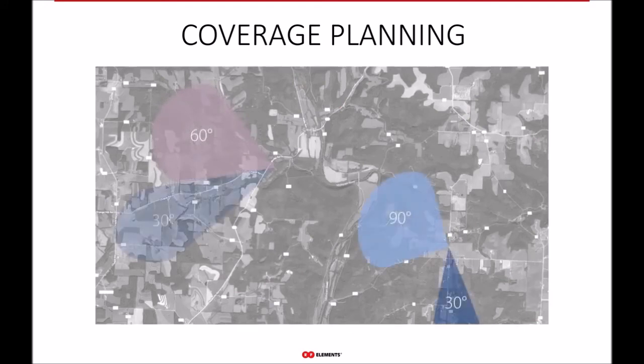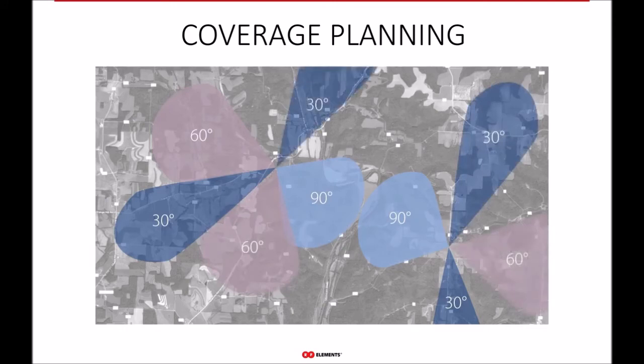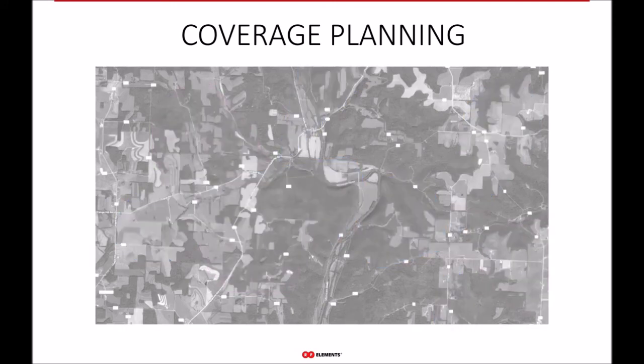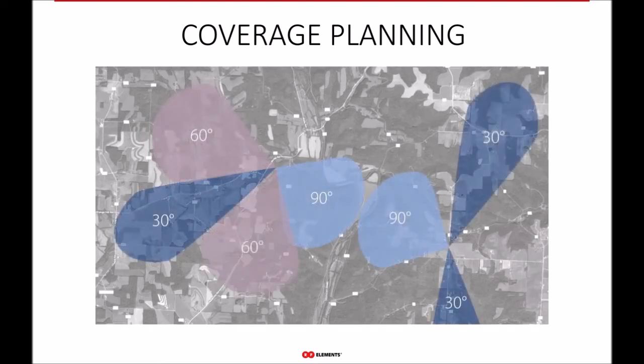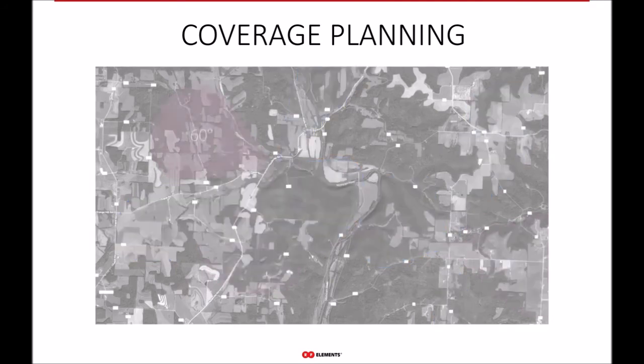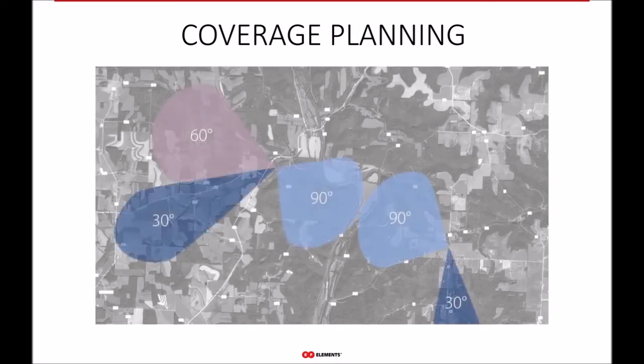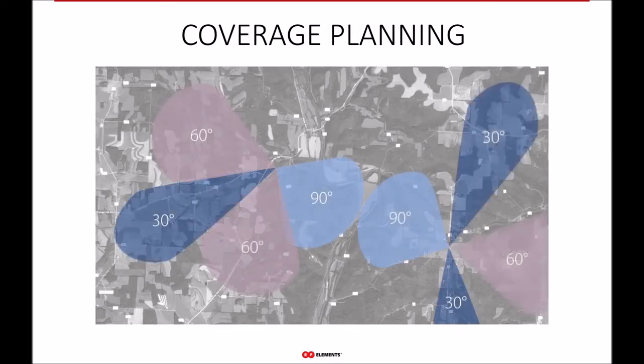When you need more gain and have more customers close to each other in a densely populated and urbanized area, you want to go narrow with the beam width. But when the customers are more sparse and not so far away from the site, a wide beam might be more handy.